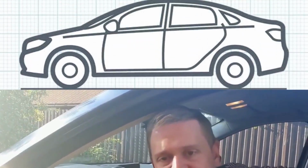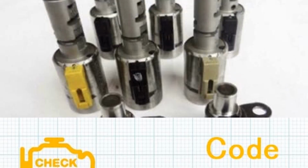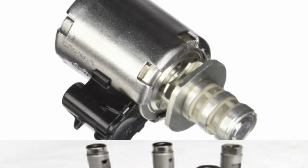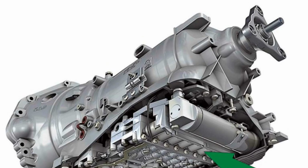Enough jawing, let's dive in. Fault code P076C OBDII is set when the control module, PCM, detects a problem in the H-shift solenoid valve circuit. Most automatic transmissions have at least 3 valves that are labeled A, B and C. The shift solenoid valve circuit is designed to control the operation of the shift solenoids, to control the movement of fluid between the various hydraulic circuits and change the gear ratio at the appropriate time. This process maximizes engine performance levels at the lowest possible revs.